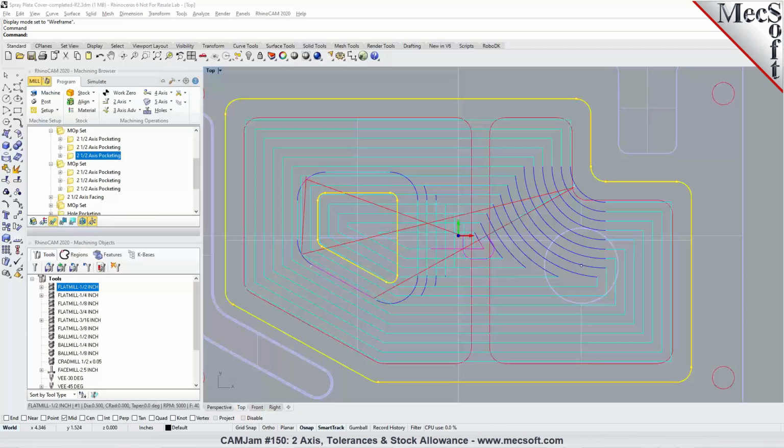So in some cases, it might introduce some errors because we are using an additional tolerance on top of your machining tolerance. If you're machining an arc, it's possible that our arc fitting will give you an exact arc. But in other cases, let's say you're machining a NURBS curve and we fit an arc to the resulting toolpath, that might result in a little bit of error. So you have to be careful about what we call tolerance stacking, because you have a machining tolerance, and on top of that, you have the arc fitting tolerance. I hope that makes sense.